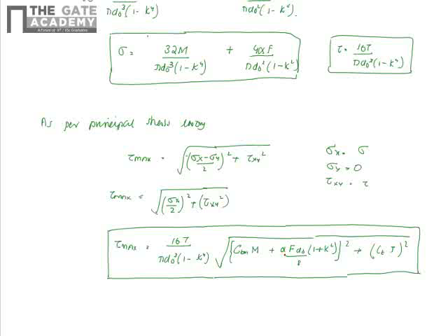Alpha is the column load action or column action factor. F is the axial force acting on the shaft. Do is the outer diameter of the shaft, and K is the ratio of inner diameter to the outer diameter. So this is the maximum allowable stress in a shaft when it's having a combination of normal and shear stress. Now we'll try to solve some problems so that we can appreciate the concepts in a better way.